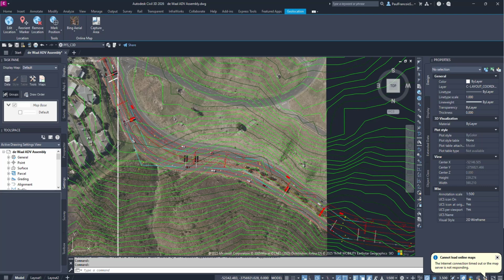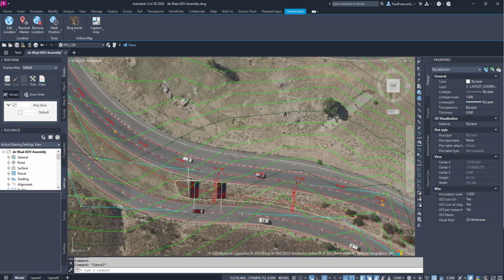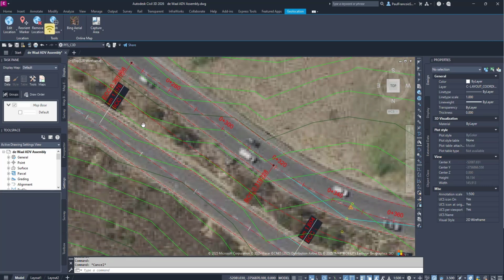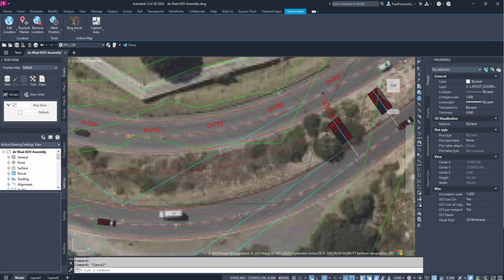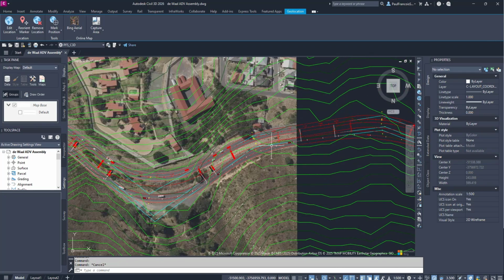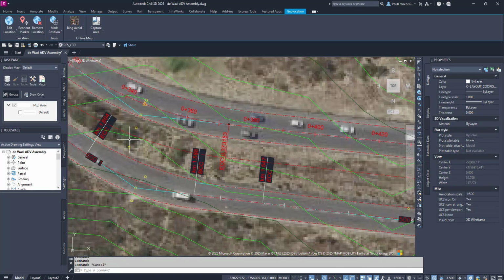This morning I'd like to discuss the assignment of speeds on alignments and how you can achieve that in practice. Usually, unless you do something repeatedly, you don't get to experience the software's nuances or little tricks. In this case, the ultimate purpose, which I have since achieved, is to create a divided crowned highway for super elevation that is going along a mountainside, and you can see it is already existing. So I'm reverse engineering this highway for myself.